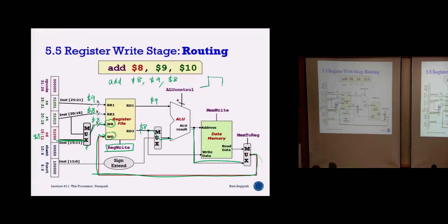As we have seen, your system is clocked continuously by a system clock. If I say I'm positive edge triggered, then this is where I will start to execute the instruction, correct? And in all likelihood, this stage here will be completed within the first half of the cycle. That means I can complete my write back in the second half of the cycle.